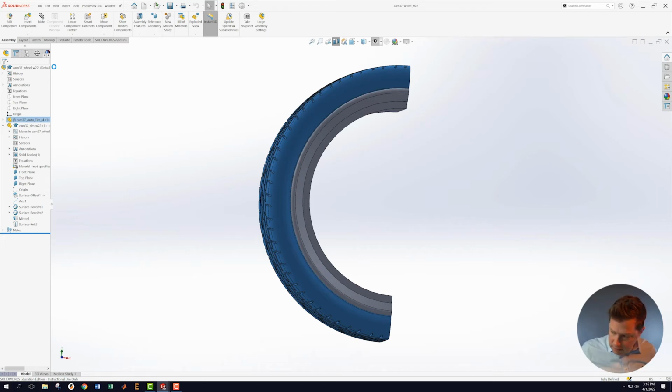So I'm reading now in the drawing. I just need a second to read this. There's a major note about the spoke. The spoke feature is a smooth loft between four cross sections. Section 1 is closest to the center of the rim and is located 2.3 inches from the center of the rim. Section 2 is shown at section CC.